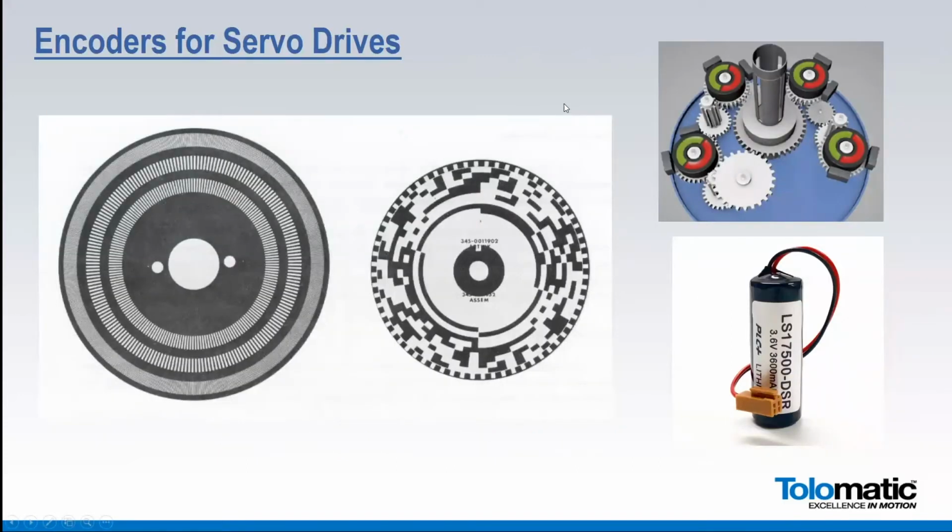So getting into the different types of encoders, particularly absolute encoders, the disk you see on the left here is an incremental encoder. So it just has the pulses, or slots, going around it. If you want to measure the rotation of your motor, or you want to know where it is specifically within one rotation, you need a different kind of way to do that. And one way, in the middle of the screen here, is an absolute encoder disk that actually puts out a binary or BCD value. And this works well, except that you need one set of wires for each of those tracks. So you can imagine if it's a 12-bit track, you need wires for all 12 of those, and you probably need the differential, so the A and the A naught for each one of those. So these have lost popularity just because the cables get so big.